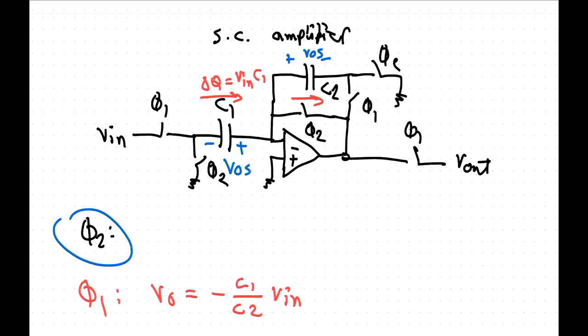If you look at cascodes, traditionally you can just keep stacking cascodes until you get sick of it or run out of voltage. You can't do that if you have gate current, because you're going to load it. That's going to limit how high an impedance you can get. It also limits the matching you can get, because the gate current causes mismatch. So this is quite important. It's a significant change.